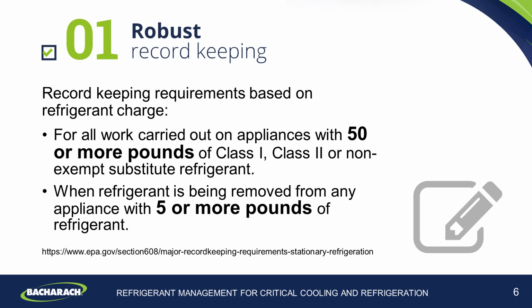Whenever you add refrigerant, the leak rate must be recalculated, but we'll come on to that in just a moment. Also the results from any inspections, checks, and verifications are needed, and any plans for retirement or retrofitting the appliance, and the schedules for those activities will need to be demonstrated.